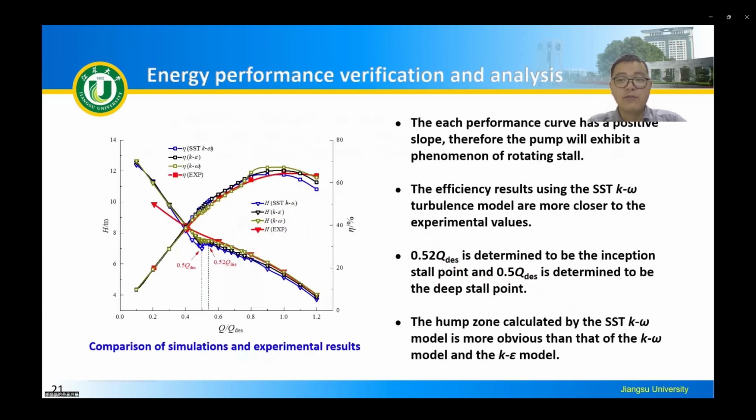And then we also find that each performance curve has a positive slope. Therefore, the pump will exhibit a phenomenon of rotating stall. The efficiency results using the SST k-omega turbulence model are closer to the experimental values.